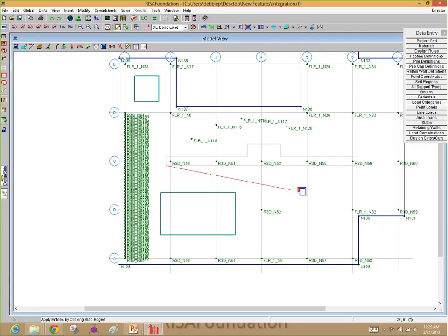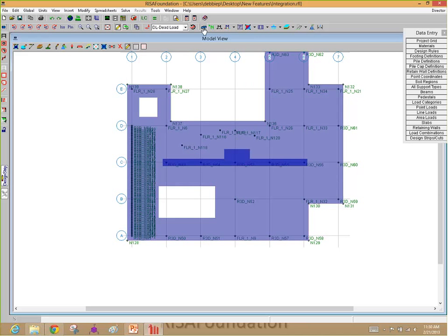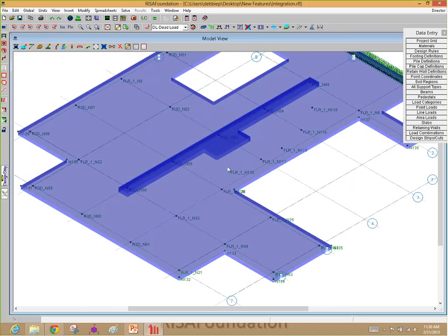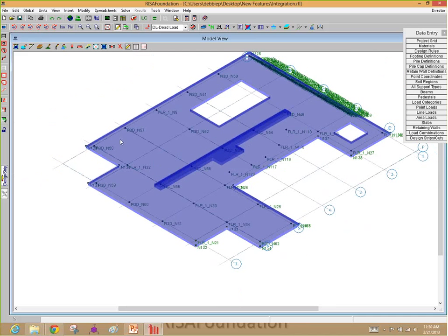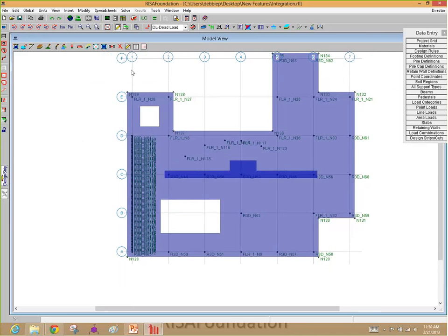In this case, the polygon really makes sense since we're going to work around a polygon shape. So I'm going to click on the different outlines of this DXF grid I imported and click around here, and I will finish that off with a last click, and I see it changes color. Now, that helps me indicate that it's thicker. What I also can do is double click on it. The rendering, see a little bit thicker there, and I can see exactly what else is showing there. You can also use plot options to display the thickness so you know what thickness you used there. So I've got a bunch of different tools now to help me modify this slab, which is really great.